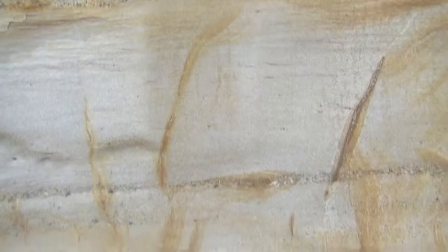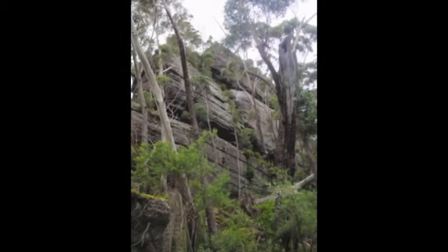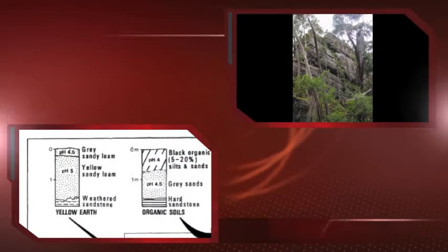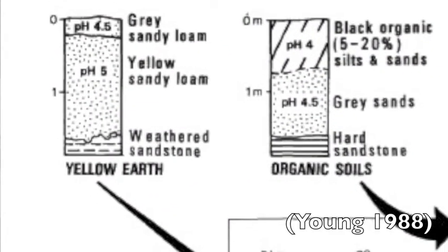In this section of the report, I will explain the types of soils found in different areas of the Illawarra and some of their applications, the first of these being the sandstone plateaus. 2 distinct plateaus being the Hawkesbury sandstone stretching from Sydney to Cambewarra Range and the Nowra sandstone over the Shoalhaven district. From these, various soils develop: skeletal soils found all over the plateaus, small rock fragments, and the sand.